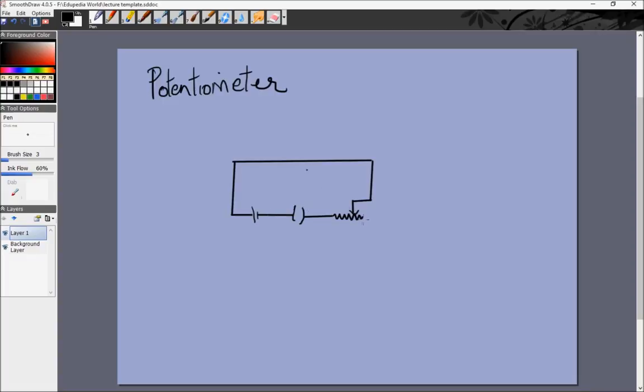And this is what is called a rheostat. And this is the symbol, and that's nothing but a variable resistance. So normally you would have a resistance and the circuit would be completed like this. All this says is that it's a variable resistance. You could basically put this arrow in the midpoint, so the resistance used in the circuit would be half the original value. You could put it at 1/10 the original place, so only 1/10 of the resistance will be being used. And since we know that resistance is equal to rho L by A, it is proportional to the length, right?